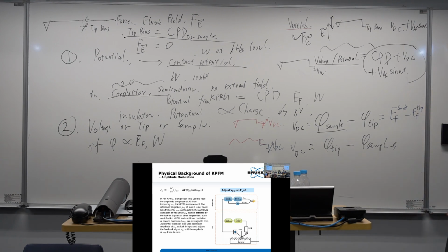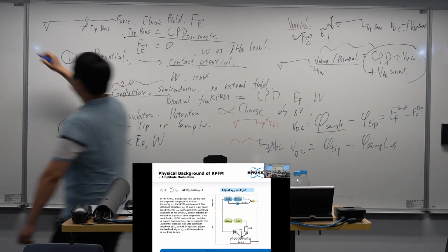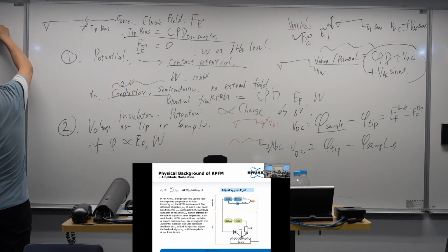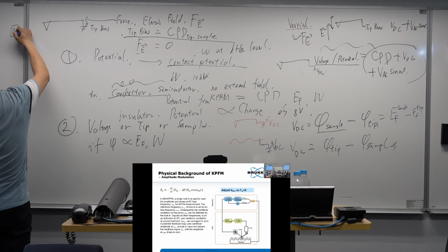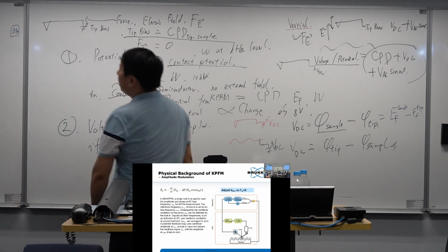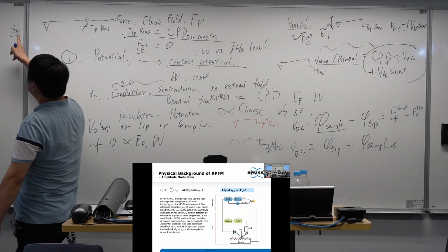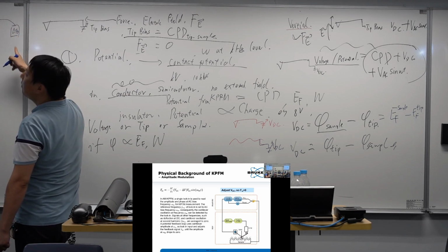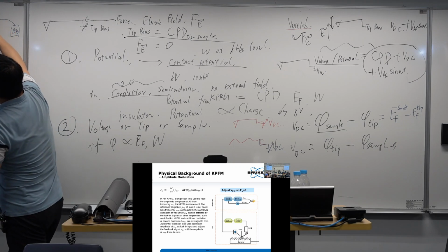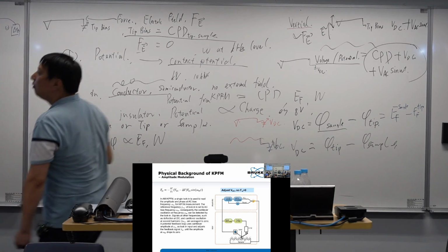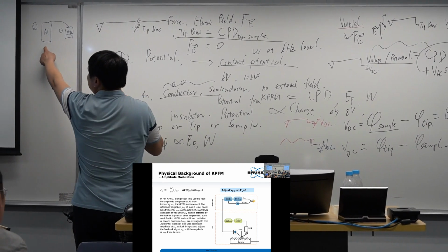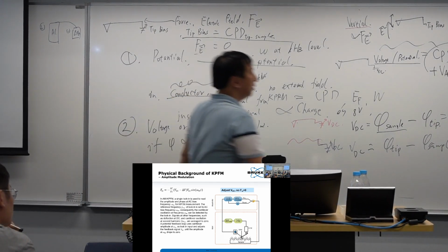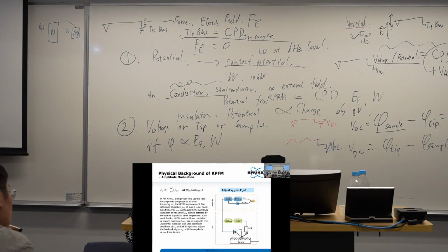The higher Fermi level will make the surface potential higher. Remember the idea of aluminum and gold. The Fermi level of aluminum is higher than gold, so the electrons will go from aluminum to gold and make the aluminum positive and the gold negative. So the aluminum will be higher potential.